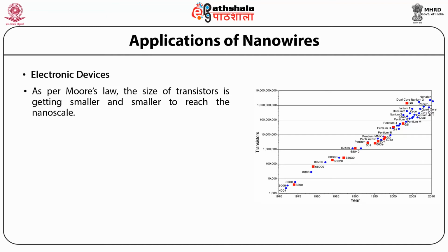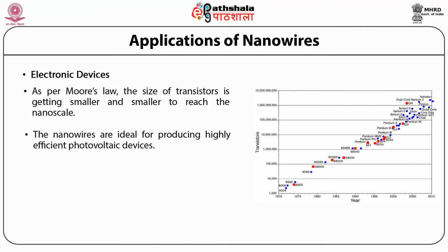Owing to their large aspect ratios, nanowires are ideal candidates for channels in transistors. If gate dielectric is wrapped over the nanowire based channel, a high gate control over the channel electrostatic potential can be achieved, leading to efficient operation of the transistor.